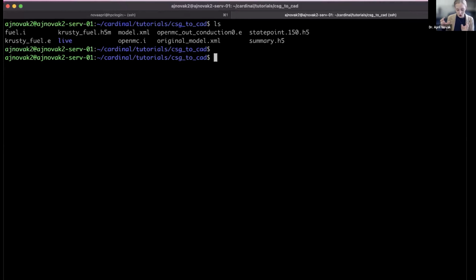So we're going to solve OpenMC to predict power that will get passed to our heat conduction solver, which uses it as a power density. That solver will then compute temperature and send it back to OpenMC. So when we go to run these files, you're going to see that back and forth solution of OpenMC, solution of Moose, where they're then passing data under the hood.